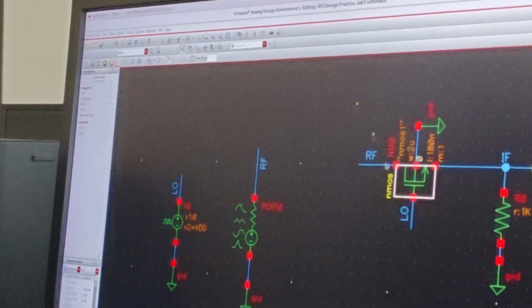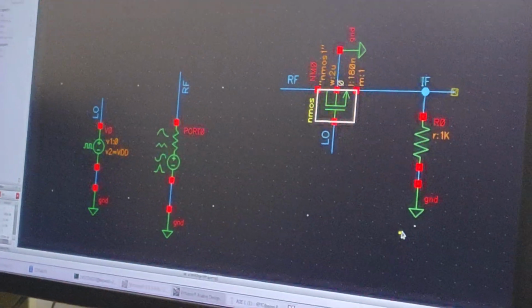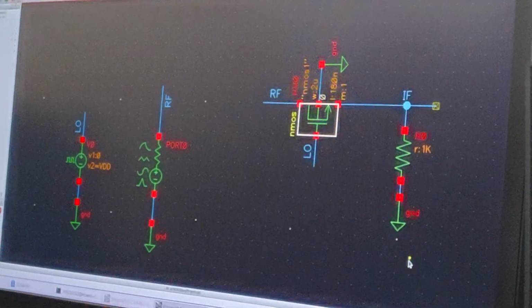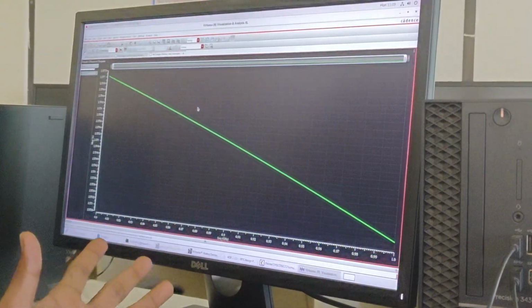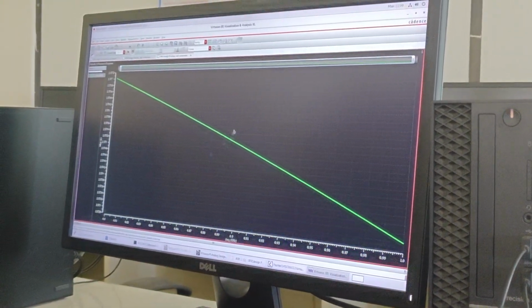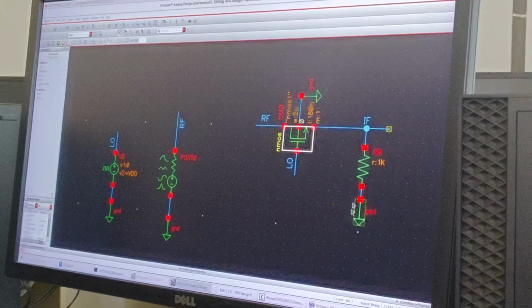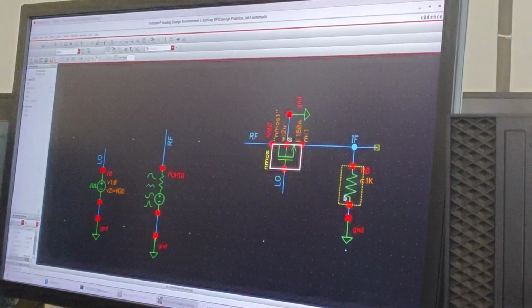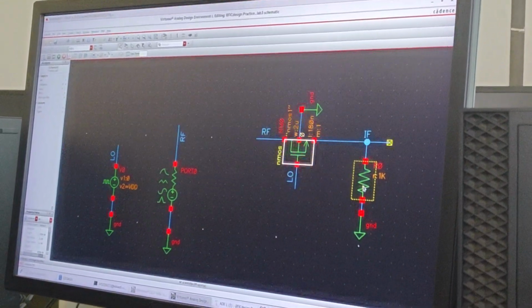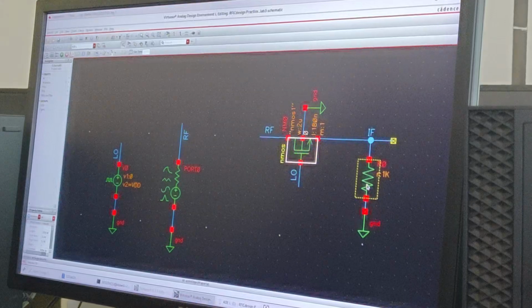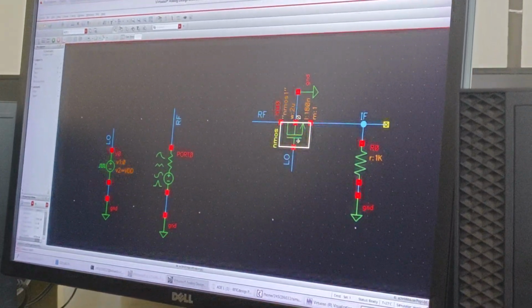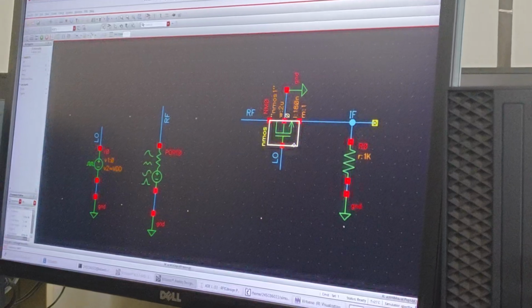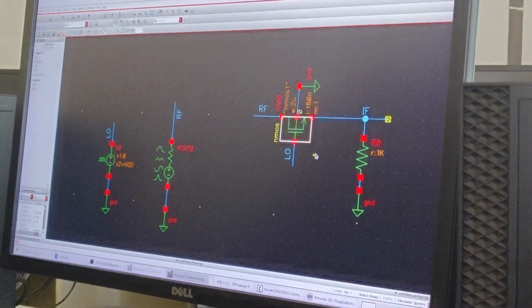So maybe because of that it will have some on resistance, and because of that you got some Z profile, some 2.5 kilo ohms on resistance. Along with that, this resistance effect will also be there. When you are doing simulations, just play around and check what this resistance effect is, what this switch effect is on the impedance and all.